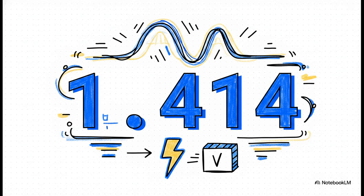So, going all the way back to our very first question, when your charger says 120 volts, that is the RMS value. The actual peak of the wave inside your wall is much higher. It's actually around 170 volts. Crazy, right? But effectively, it does the exact same work as 120 steady volts.